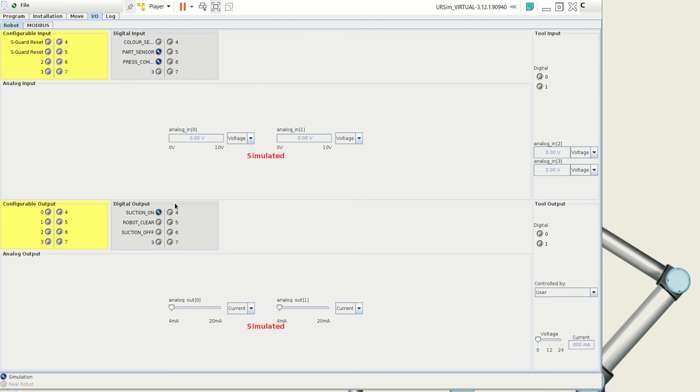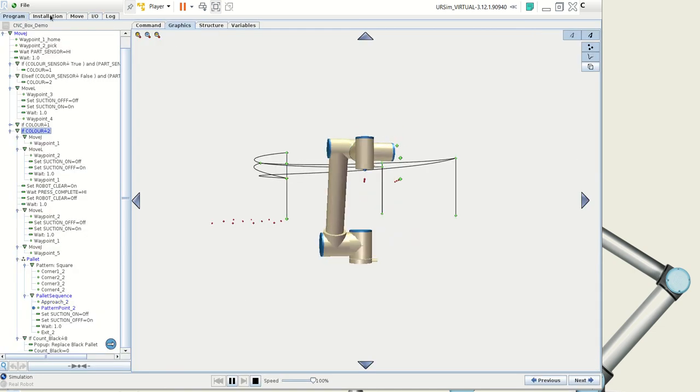That could be fair enough, as you might want to do that. You could look at maybe more efficient ways of using a vacuum sensor as well, so that once it detects that the part is fully sealed on, you don't need to keep the suction cup on the whole time. And we've seen that in some of the labs that we have with the actual robot itself. So it's just some other performance enhancing that we could look at.